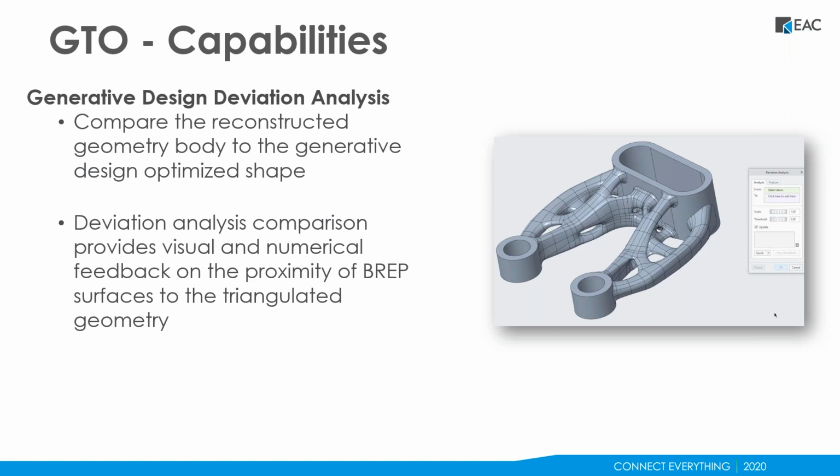What's going to happen here is you're basically doing an analysis with an internal mesh that's going to do the computations and figure out where I need to have material and how much material I need to have, and it'll create this triangulated geometry. From that, it's going to wrap that geometry with a Creo freestyle type feature, which can then be solidified to give you the resulting final geometry.